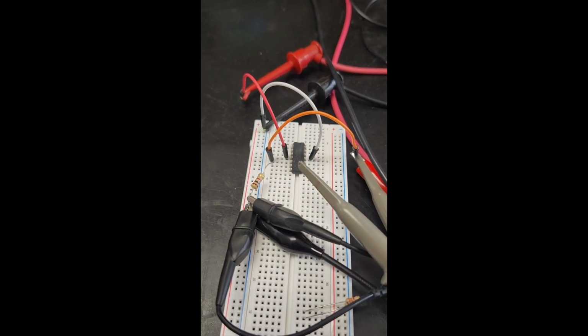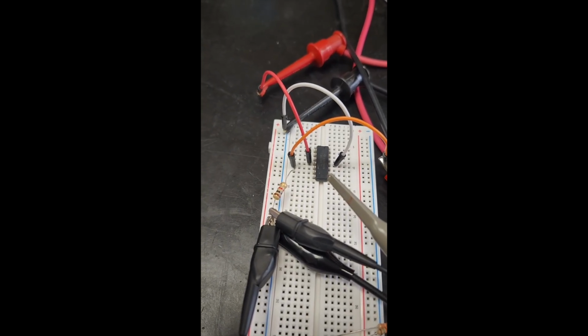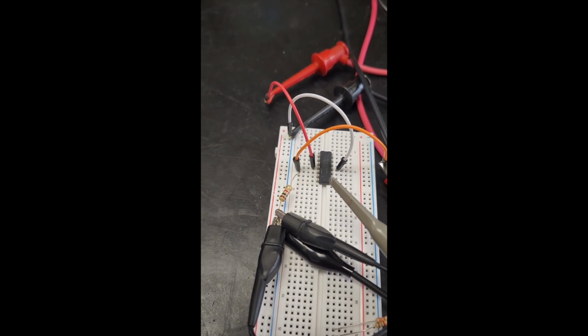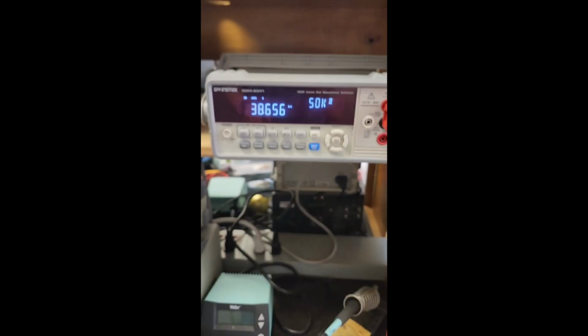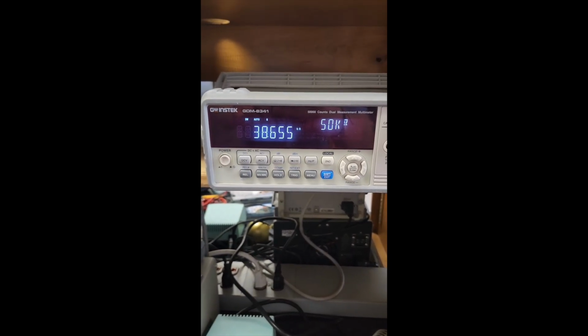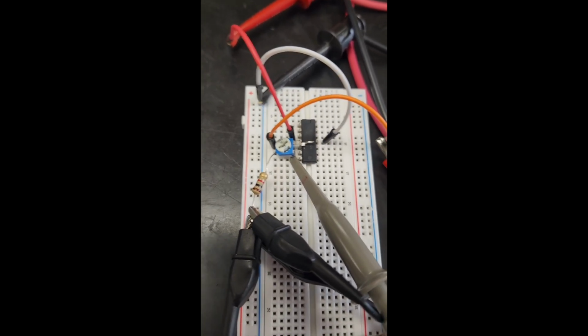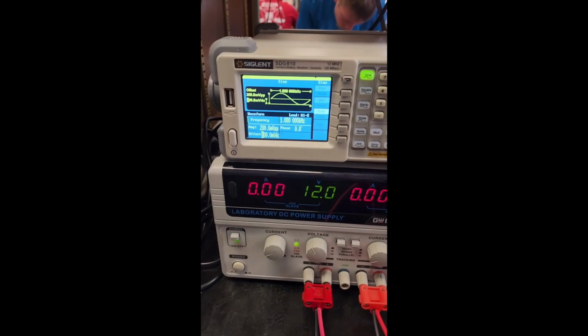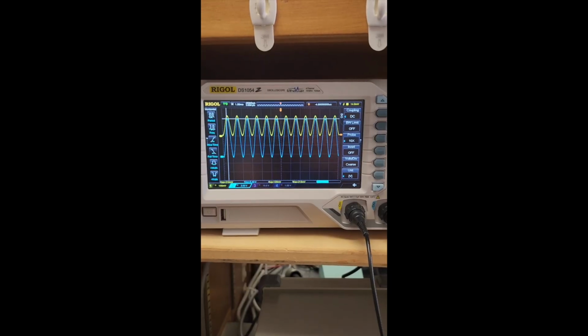And so here's our circuit. We have our VCC hooked up with our 1 kilo ohm resistor going into the non-inverting terminal. And then we have our potentiometer set to 39 kilo ohms, which should be our max. After inserting our potentiometer back into the circuit and hooking up our oscilloscope, setting our VCC to 12, and our function generator to these values, we can see our different gains, as the yellow is our input and our blue is our output.